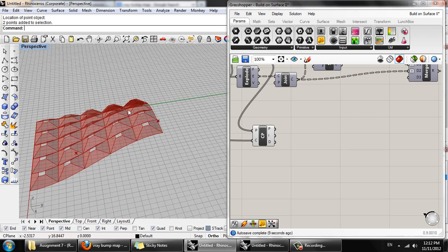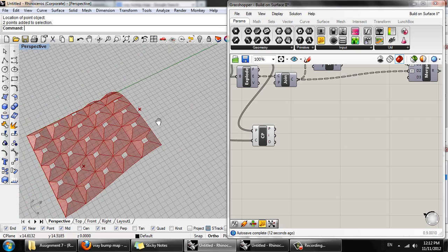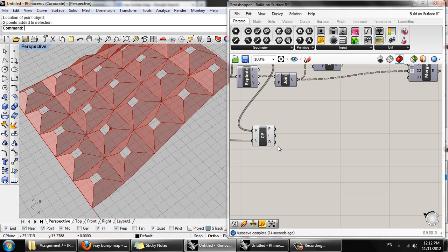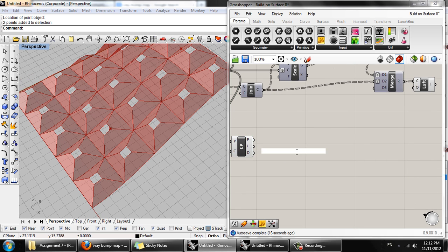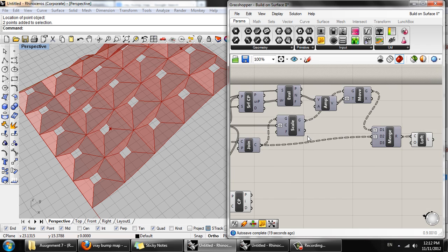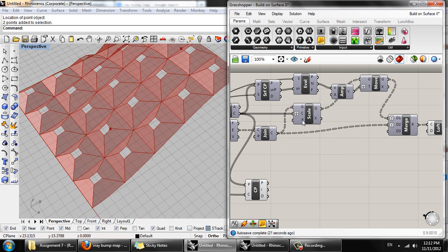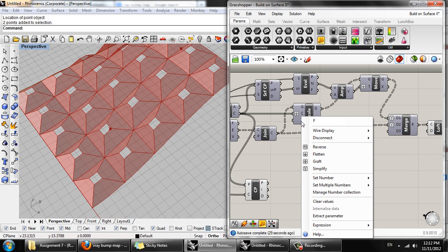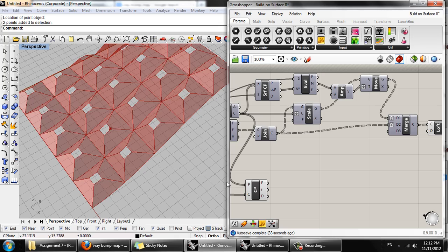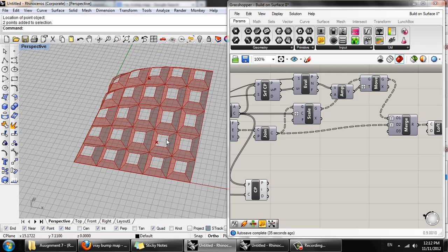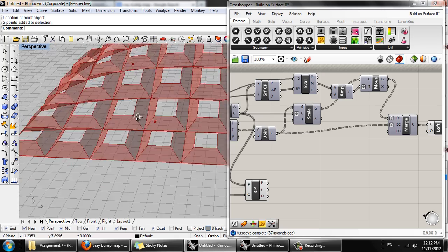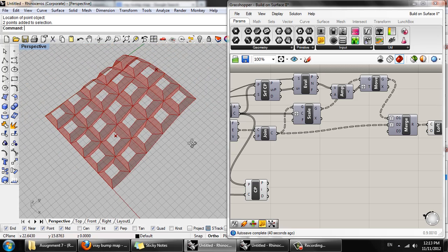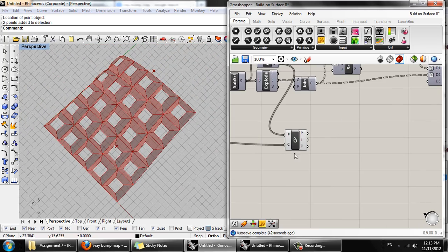We can remap that into values, say, for let's say the scale factor, and so that we can change what here is a consistent scale factor of 0.25. Of course, we can change that manually, but instead of having a consistent factor here, we can make this a variable that changes based on the proximity to the attractor point. Okay.